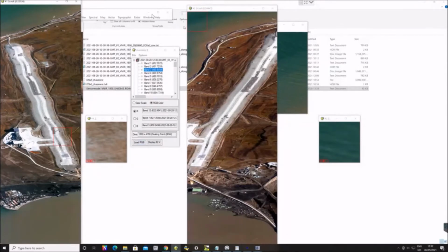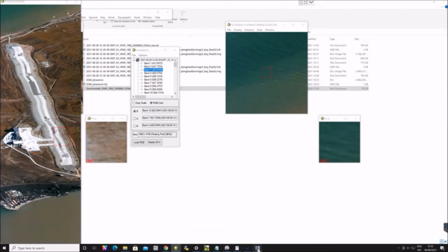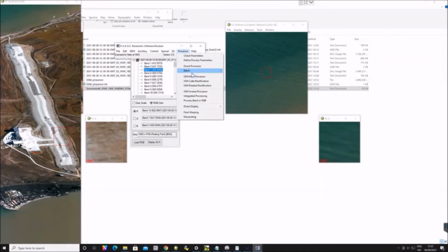Then we will start with the georeferencing of those two without any Boresight. So then we are just georeferencing them in the coordinate system of the INS, not with the correct Boresight rotation. This Boresight only has to be done once for each installation. Once you take out the camera and put it back relative to the IMU, you need to redo it. But if you keep the installation stable, there should be no need to redo the Boresight.